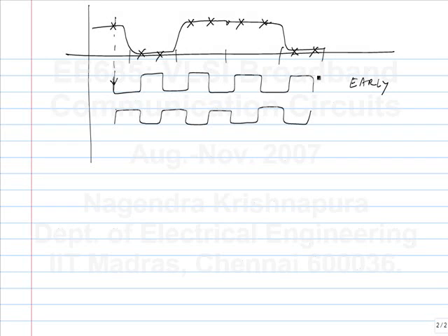Right, you sample with the rising edge or the falling edge. My eventual goal is to tell whether the falling edge is before the data transition or after the data transition. So which samples do you take? I think people have been saying that you need 3 samples, not 2. The 3 samples can be all from successive rising edges, successive falling edges, or 2 from a falling edge and 1 from a rising edge, various combinations, right? So which one? 2 rising and 1 falling. So if you have 0, 0, 1, or 0, 1, 1, then it is 0.